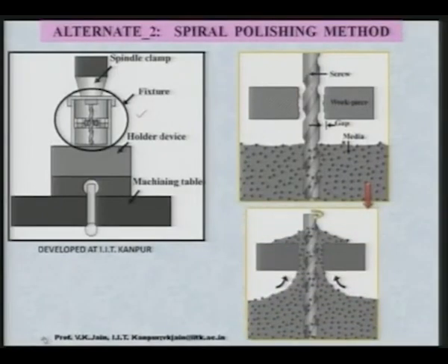And the situation when the medium is passing through: this is the workpiece, this is the medium, and this is the rotating screw, and definitely this becomes the restricted area. So, the larger radial force is acting on the abrasive particle, and that force is transferred to the workpiece for higher penetration.